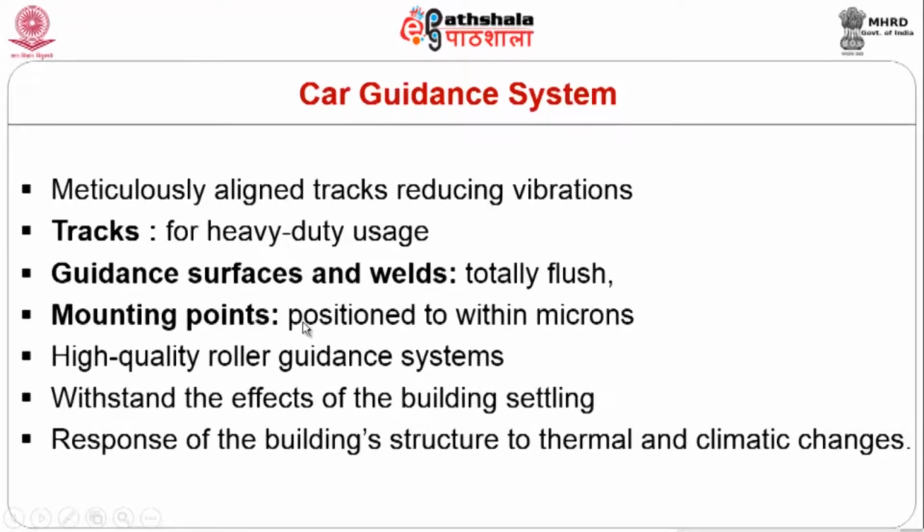Mounting points, positioning within microns, and there has to be very, very precise execution of work. High quality roller guidance systems have to be in position. They have to withstand the effect of building settling. As we are all aware, any building over a period has the tendency to settle depending on the soil condition, and as the years pass, as decades pass, there are issues of settlement, and these elevator systems have to take